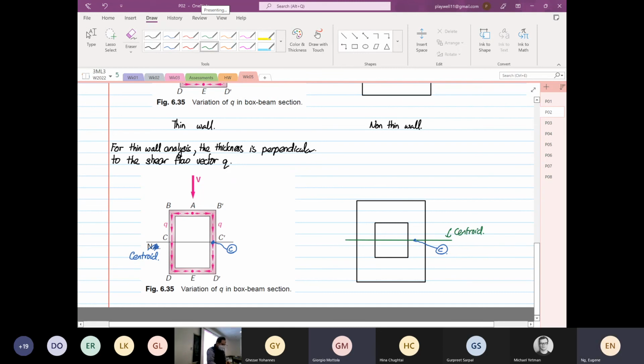All right. So now we want to find the shear stress. So the area to consider, what we usually do is we divide the area in such a way. We divide the area in this way. We find our Q, and then we divide in the other way. This is the other Q that we find. Okay, so that is the area of consideration. Then the thickness is this thickness.